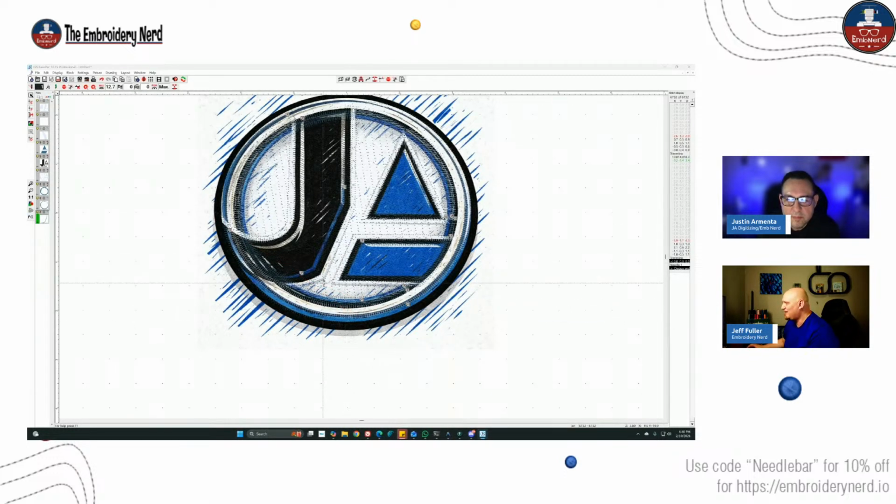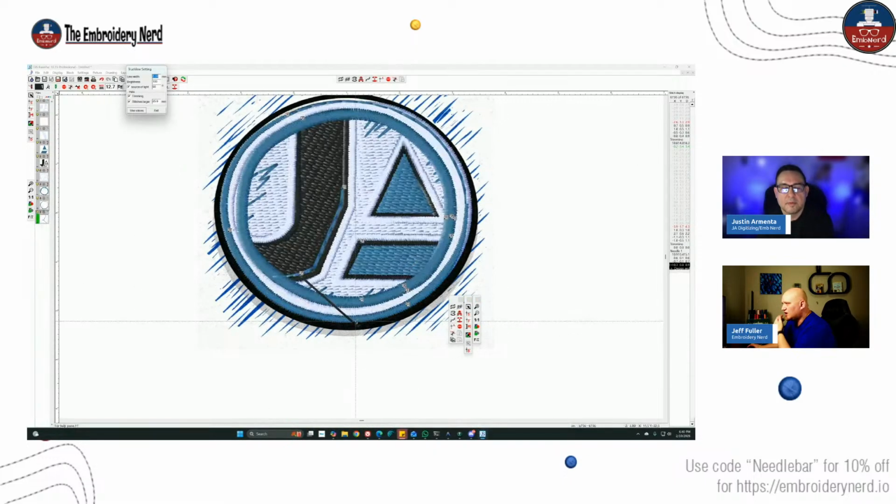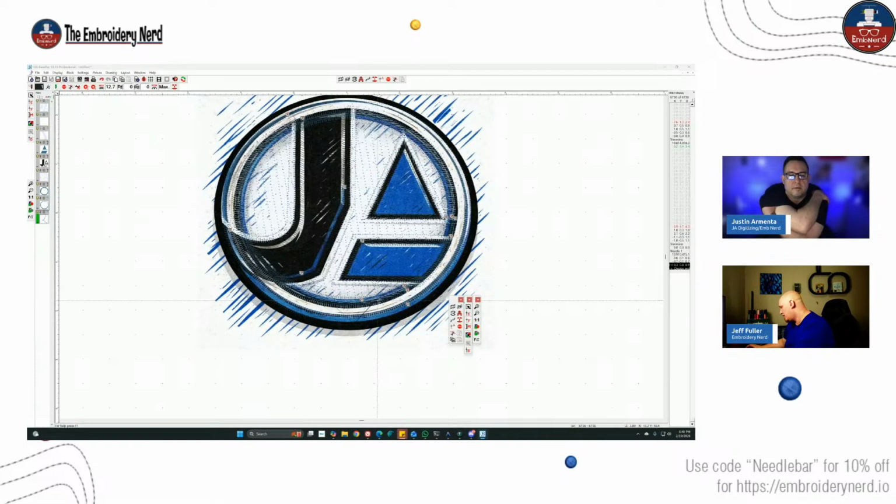So we've got the needle change. We've got the trim. So now if I come in here, I can do that. But that can be frustrating sometimes when I do that. I'm just going to check and see, it did add that needle change where I didn't want it. So let me go ahead and clear that out. So I got that trim. There. Now I'll throw the trim, and then I'll do the needle change. And now we won't have that.